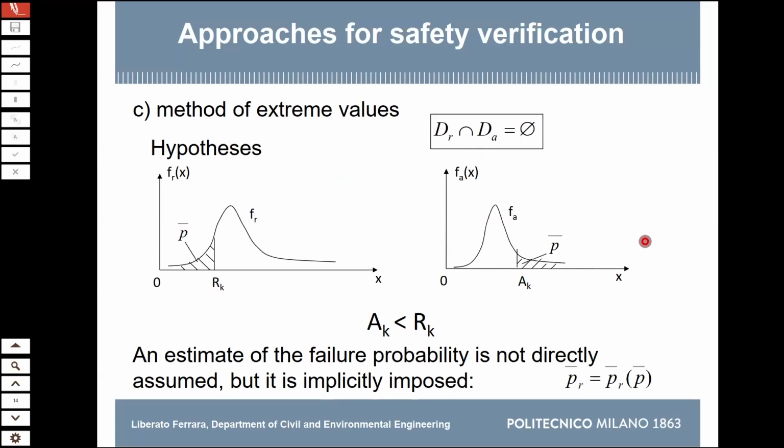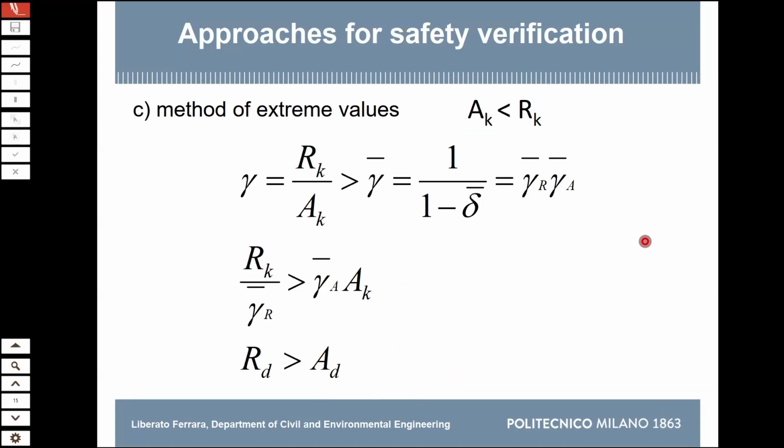Yeah, well, we have to accept that if you write the function, it has values on the negative, but they are so low that you can neglect it, or we accept a curtail at x equal to 0, because we are dealing with strength, and the strength is intrinsically a positive quantity. So as I said, once we have identified these two values, the characteristic values, we put them into the inequality that we wrote before.